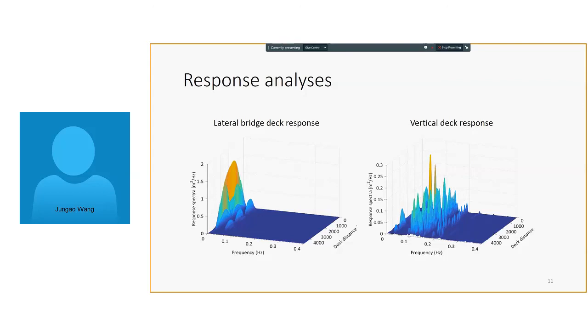It's called set-down in hydrodynamic terms. Do you have some comment on that? Because if you have a very large contribution in the lowest horizontal mode, you should also have a relatively big contribution in the vertical direction, right? Because this is what we found from Abaqus simulation.